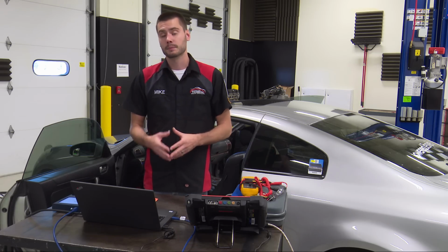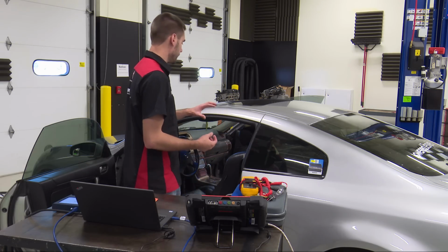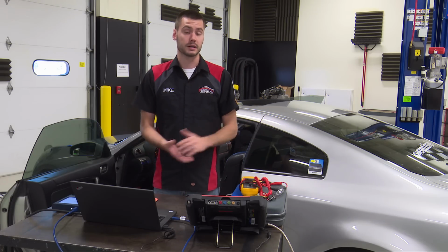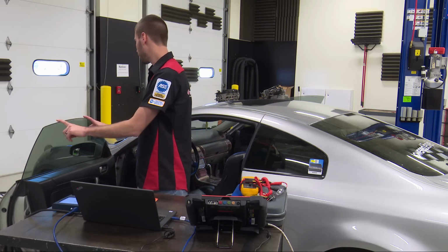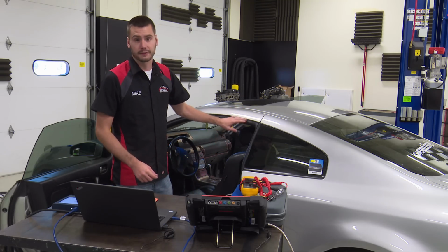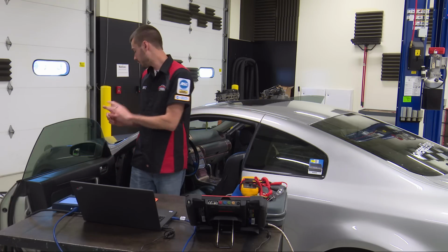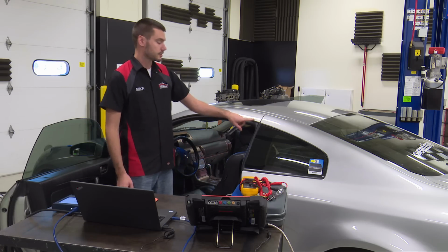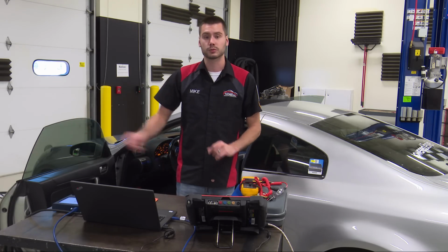This is important. If you're running into a power window issue where the window is not working, it's not moving at all, the switch might not be working, the motor might not be working, who knows what the problem is at that point, but just know that if this window doesn't move properly, it's possible that it could be stuck in the frame here. So you try to open the door and the window is stuck in the frame, or if the window is all the way up and you slam that door closed, it could hit the frame and shatter the window, okay? So keep that in mind when you're working with frameless windows.